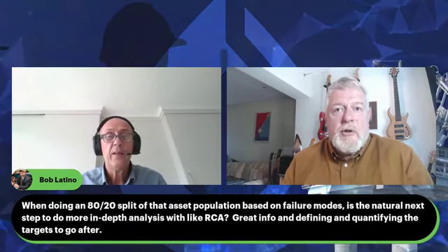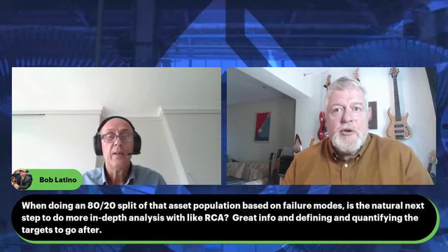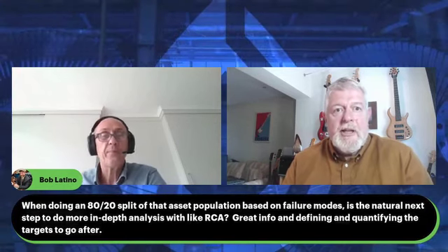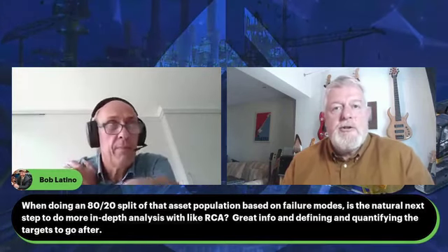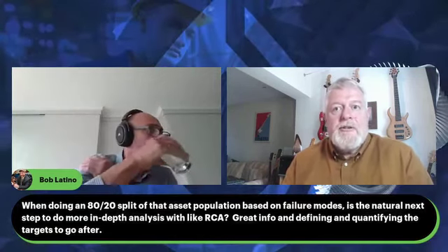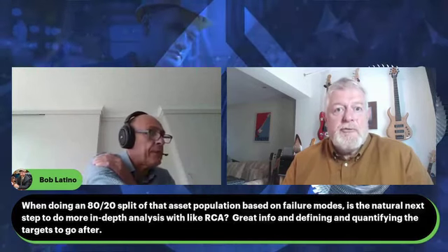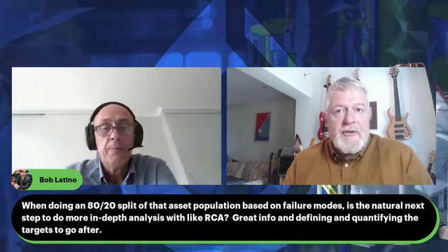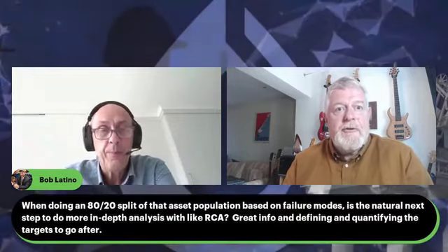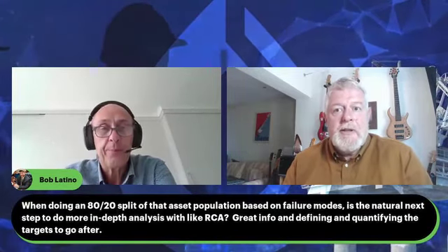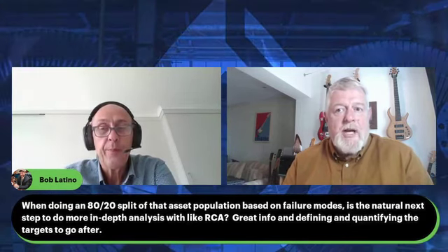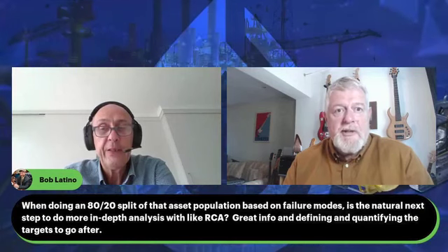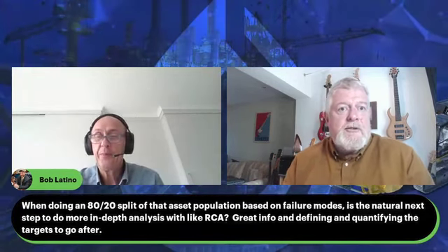Because when we set up our condition monitoring, whether it's oil analysis or any other, we're normally looking for failure modes that we're familiar with. But we can't plan for everything, so we will have failures or excursions that we hadn't planned for. And the skill there is understanding those, performing root cause, and bringing them into the known light of confidence, so that we don't repeat them. As one of my apprentice teachers told me, "I don't mind you making mistakes, but I don't like you repeating them." And that's just using data wisely, I think, at the end of the day.